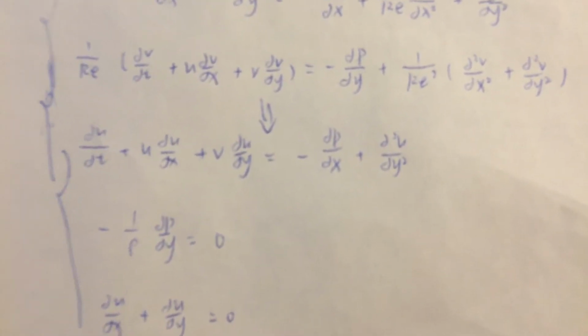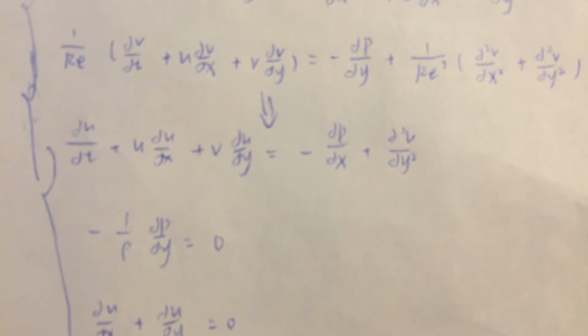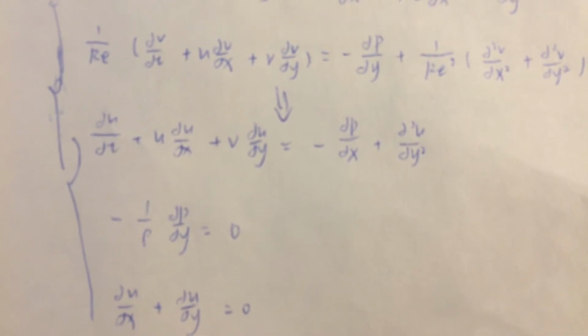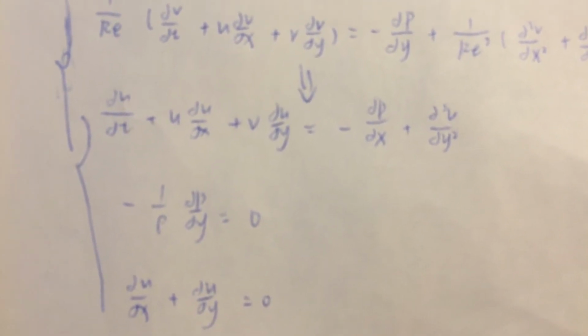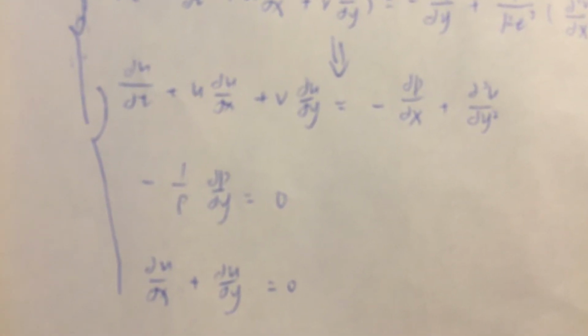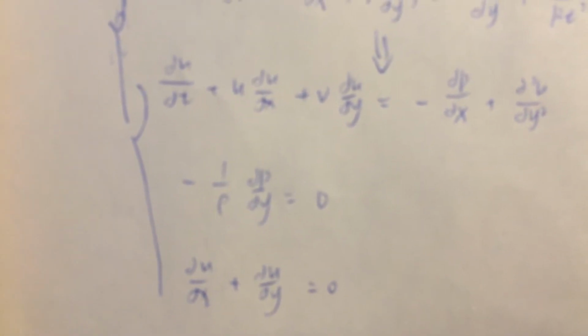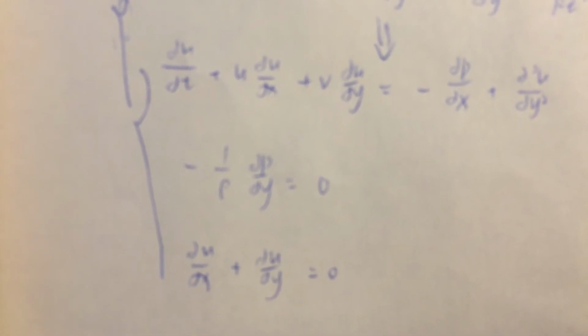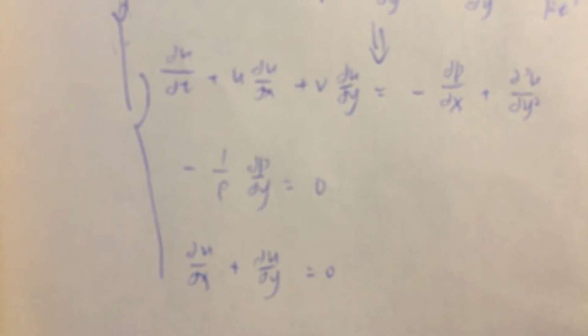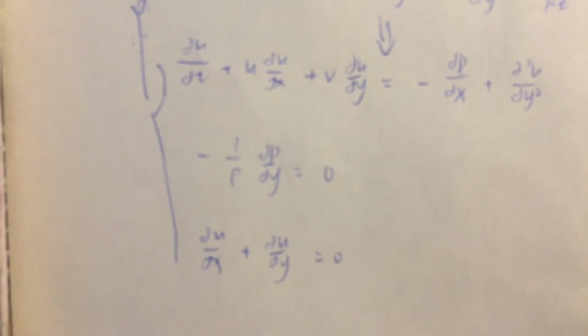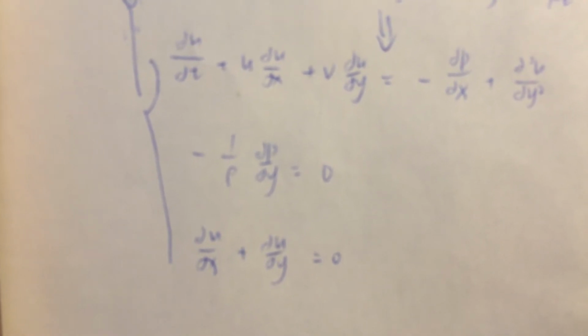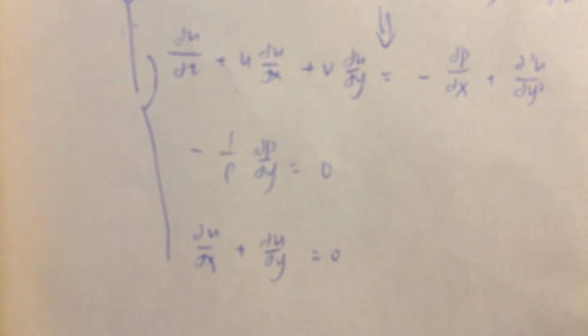The upward flow becomes so strong at some point that the fluid flowing in the mainstream direction cannot continue. So some fluid in the boundary layer will then have to flow against the mainstream flow. Between the forward and reversed flow, there will be a separation line ending on the wall. In the region of reverse flow, the velocity still vanishes right at the boundary.